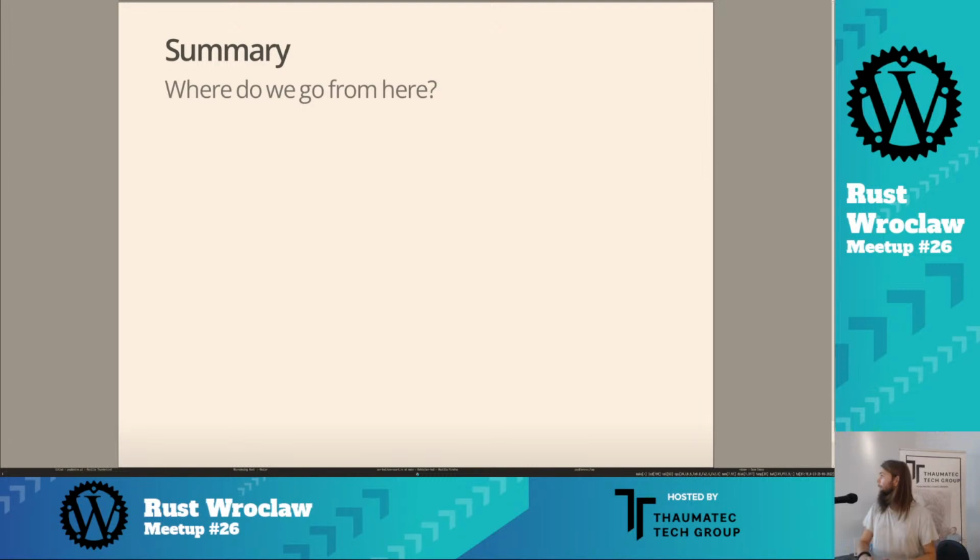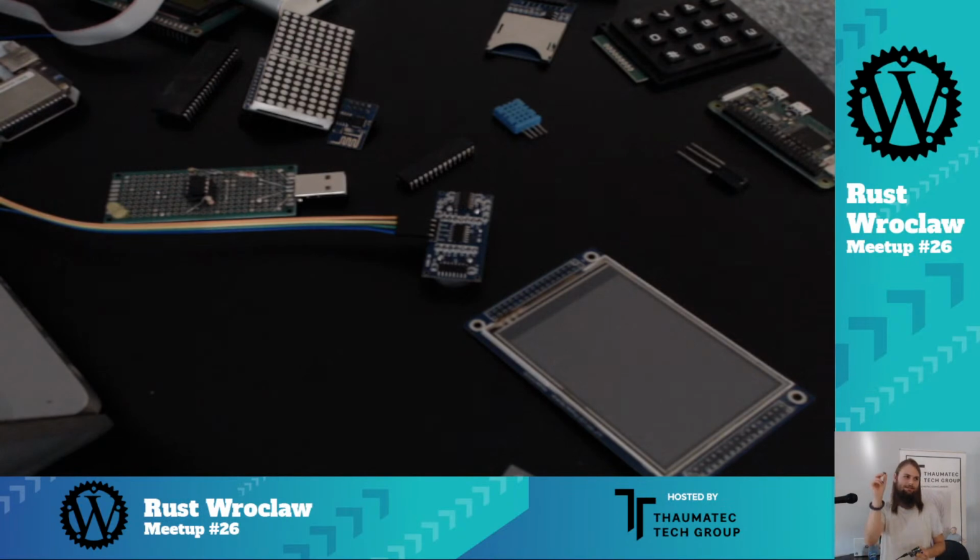Okay, so before I was doing live coding, this time I have flashed something onto the microcontroller, and I'm going to attach it to show it. This is a buzzer, a simplified version of a speaker. It doesn't require any additional power. I can just power it through the pins. Again, somebody might yell at you that you need a transistor or something. I say don't listen to them.